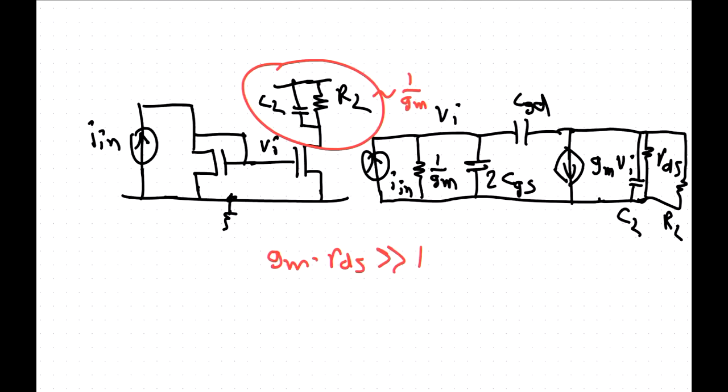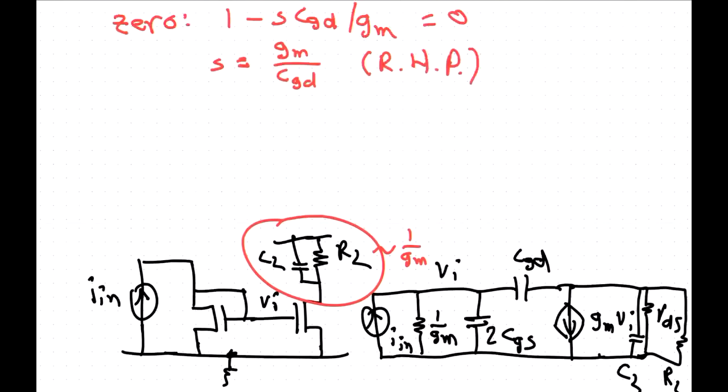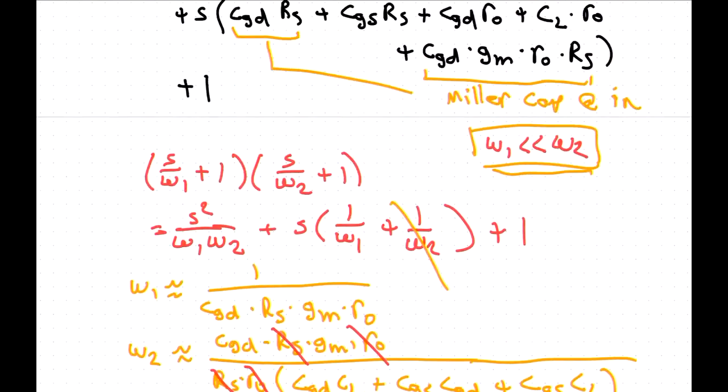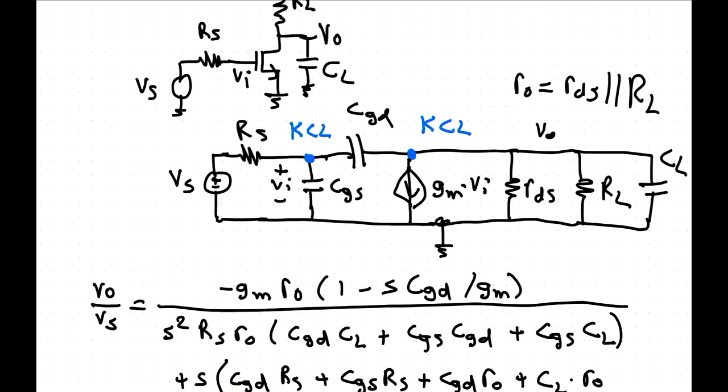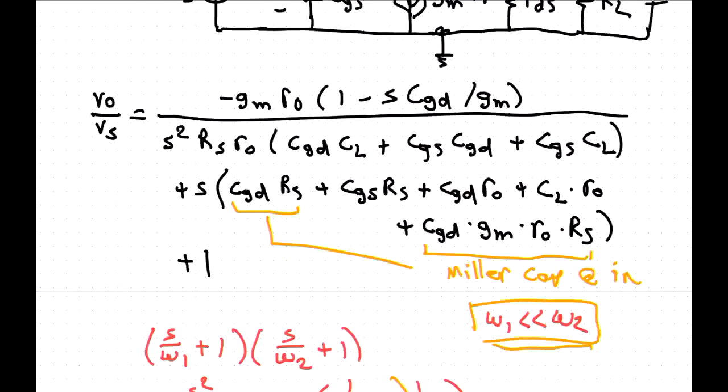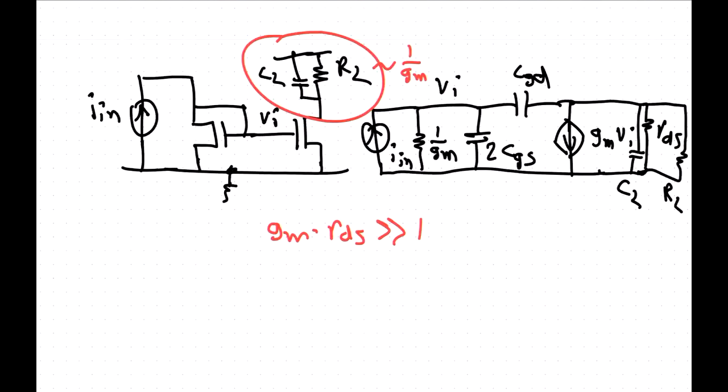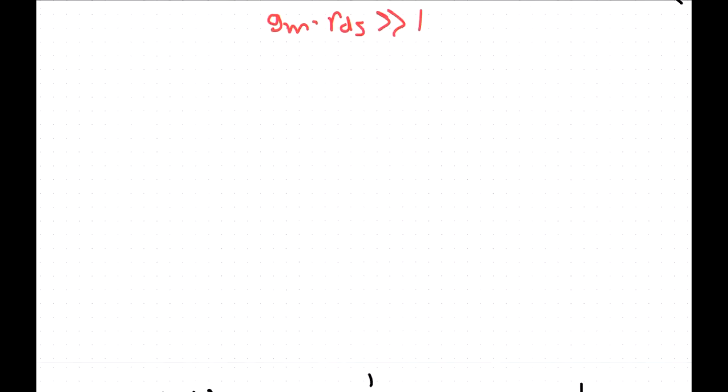If you look at a current mirror, we can actually have the same diagram as well. Which is important because for common source amplifiers, all these resistances in this small signal diagram are RDS type resistances, whereas in a current mirror, all these resistors are 1 over gm type resistances. So they are 1 or 2 orders of magnitude smaller, so the current mirror is fast compared with the common source amplifier. That's a really important point, which is why you can use a common source amplifier to analyze an op-amp and ignore the current mirrors.